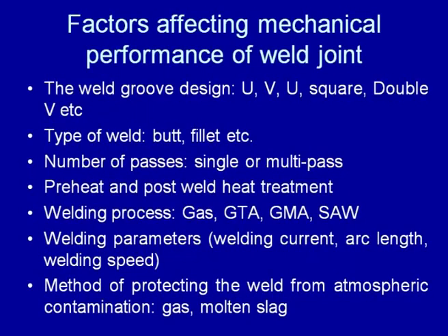That is why the best kind of mechanical properties are obtained using the GTAW weld, while SAW and gas welding processes result in higher heat input, and a weld with a lot of inclusions, porosity and impurities results in poor mechanical properties.